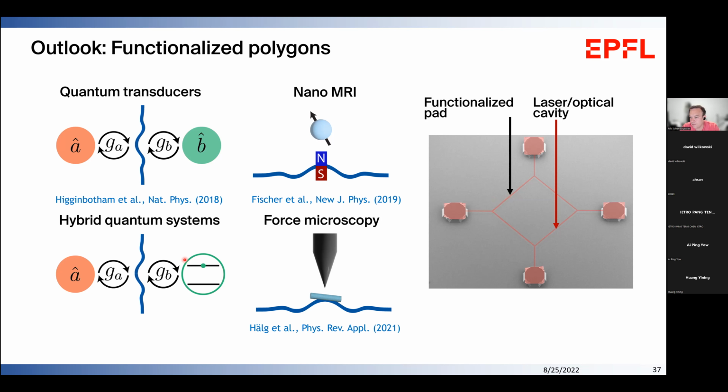Currently, silicon nitride is a dielectric, so it doesn't couple well to electric and magnetic fields, but by depositing, for example, metal or magnets, you can potentially change this. And it has been shown in the literature that such manipulation of the resonators does not necessarily degrade the quality factor too much. There's always some degradation, but not to a prohibitive extent. So that summarizes my talk for today.